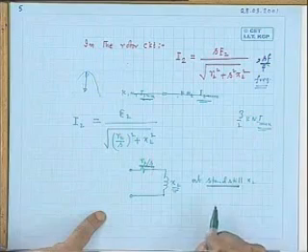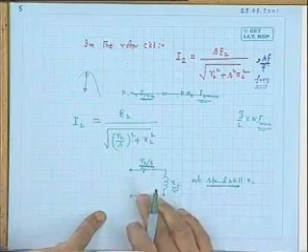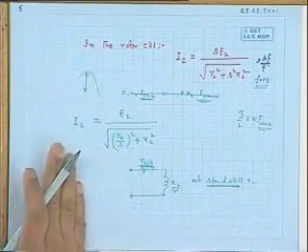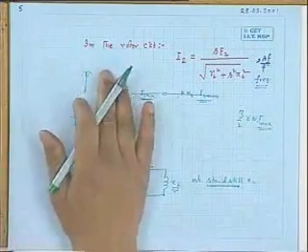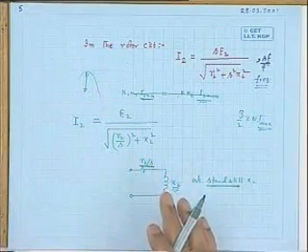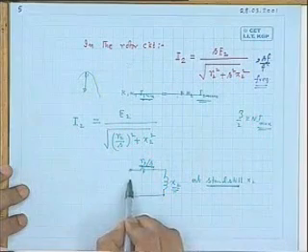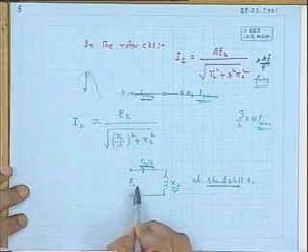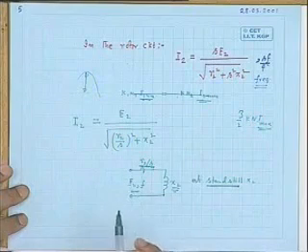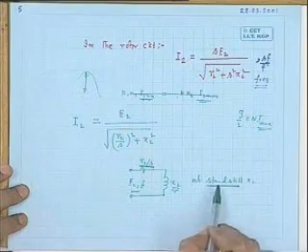That machine is under standstill condition. The rotor is just replaced by this one. Now, for this machine, the same stator winding is there as in the previous machine, and the supply is given. At that time, the induced voltage here will be E2 and the frequency of this current will be F.